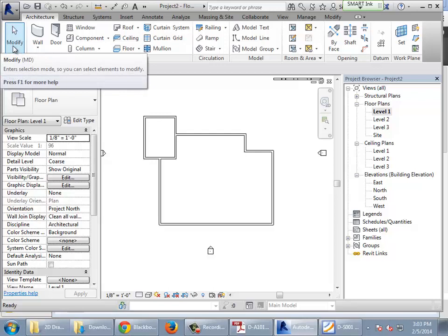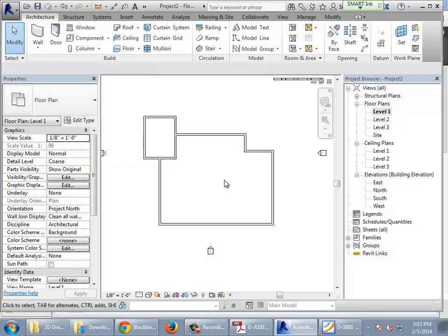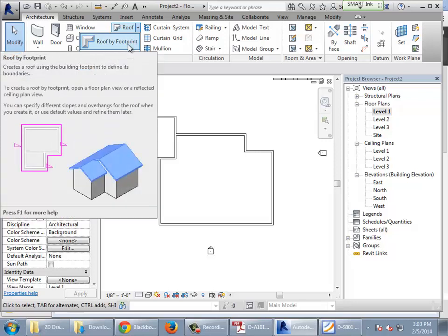More or less? Okay. So here's how we go through and put a roof on that. There's two kind of interesting holes in this whole scenario. So we'll think about this. And let's talk about this lower roof first. Roofs are really, again, very complicated objects. These are both roofs that I think you can best dictate as footprint roofs, and that is, we're going to trace the boundaries and slope up the roof from there. But there's a couple nuances to it you need.